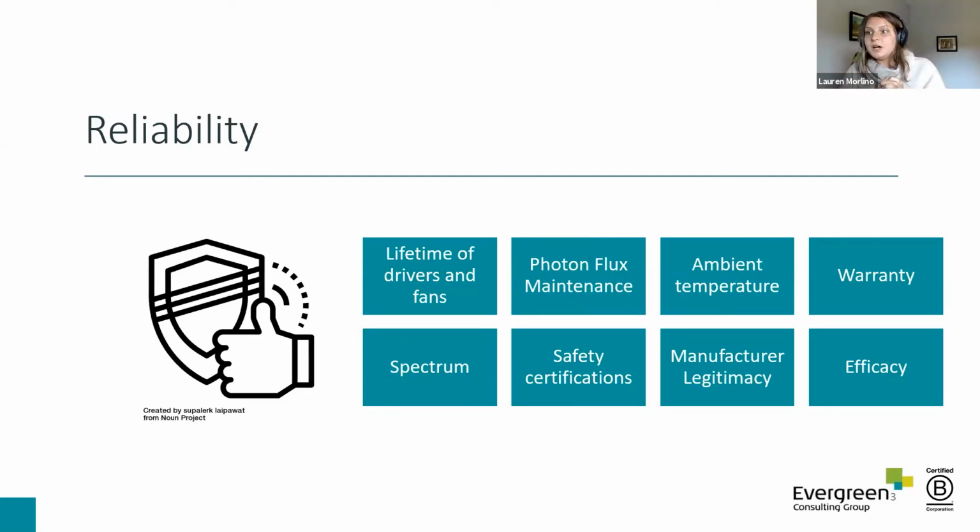And finally, perhaps most importantly for utilities, is efficacy. The lab testing that DLC requires tests actual wattage in and PPFD out. This demonstrates that the product is actually working in alignment with what the manufacturer's specifications say it's supposed to do. It allows growers and utilities to be certain that the correct amount of power is being supplied to the fixture and that energy savings being claimed and reported to whatever state the fixture is installed in are accurate.